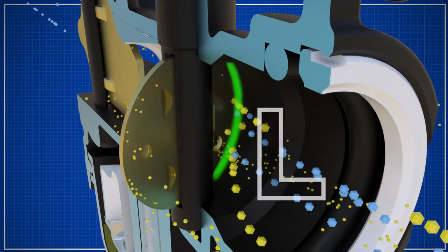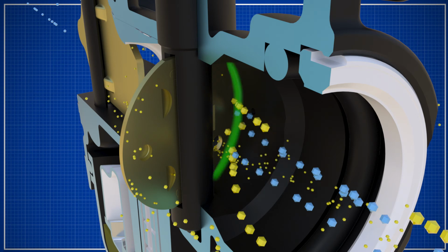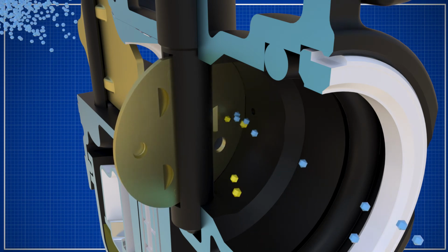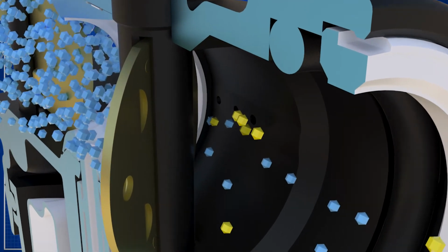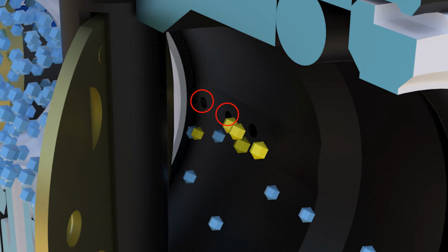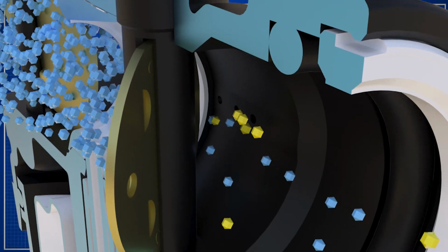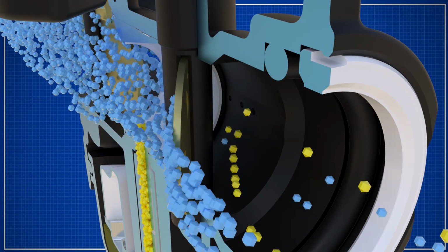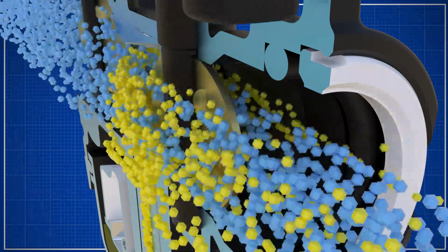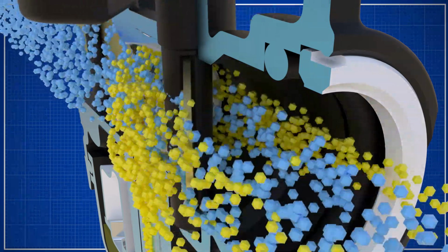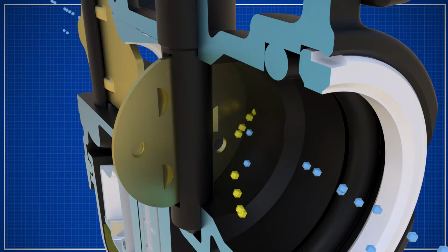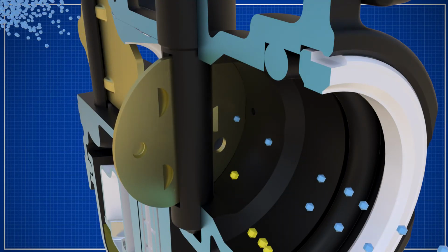While the throttle plate is almost closed, a venturi comes into shape between the edge of the throttle plate and the carburetor body. The idle fuel supply port is at this location. The transition ports are also immediately behind the idle fuel port. The transition ports supply auxiliary fuel when the throttle plate starts to open. This function creates seamless engine speed changes. The high-speed circuit is more direct.